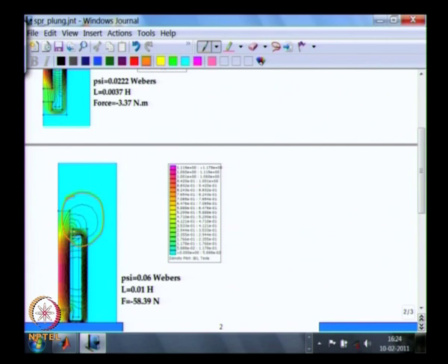It is not really flowing straight along this, but you find all kinds of field lines going out, whereas here you do not see that effect. Field lines are going straight from the bar onto the other level. This kind of effect where the field lines move out of the ordinary route is called fringing.